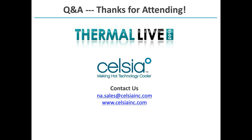Because the performance of these things changes as soon as you change any of the attributes of the application. If I change the heat source size, if I change the heat sink size, if I change the airflow, if I change any of those things, the performance of the heat pipe or the vapor chamber is going to change. What we generally do is say, we'll give you some guidelines. When you have an application, call me and I'll give you the number.